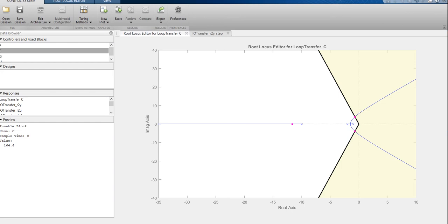Well, in this case, we need to have the closed loop poles right at the intersection of the white and yellow area, because the requirement is in terms of having the damping ratio equal to that value, not smaller or bigger than that. All right, so with that value of Kp, we have the closed loop poles here and there, and the third one will be over here.